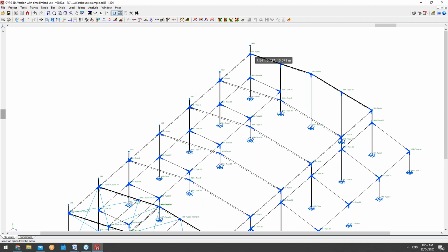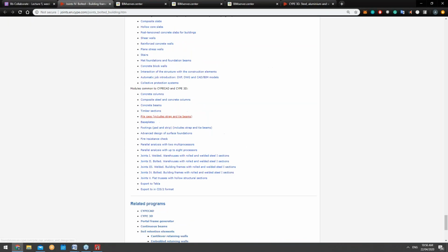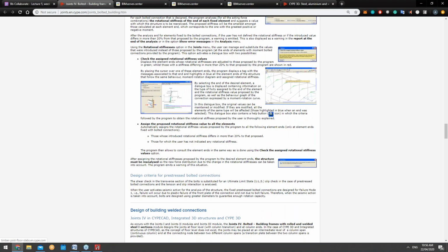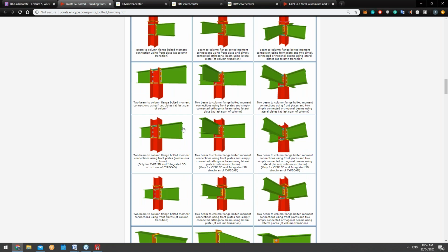Now, Ahmed, if you're having problems, my explanation to you is, one, either you have different non-simple sections that have been done, or number two, you have a connection where the connection has to be done in more than 2 planes, but we only do it in 2 planes. What I'm trying to explain is the start of the webinar, which I explained here. 2 planes. You can see here the initial vertical plane and the horizontal plane, and that's where we can make connections with boxes, box tube connections, etc. We can do those, as long as they're on 2 planes.